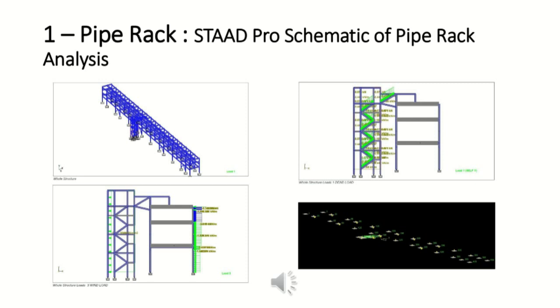Those points of support are then transferred to the foundation design. The last photo you see there are the points of support for the pipe rack and the open frame structure. Those points are then designed for the isolated footings that support the pipe rack and open frame structure. And because the soil bearing can handle it, we have used here isolated footings for the foundation support.